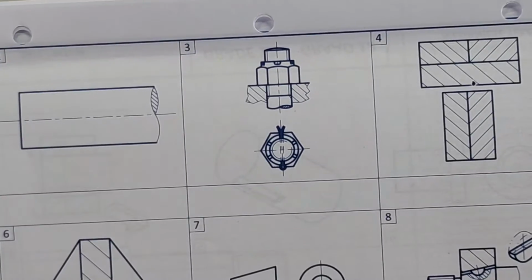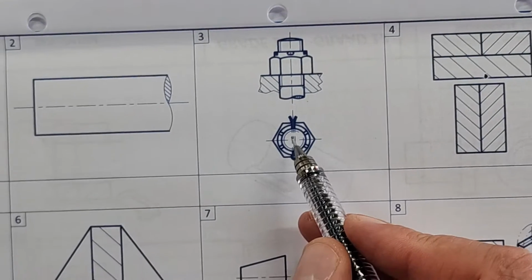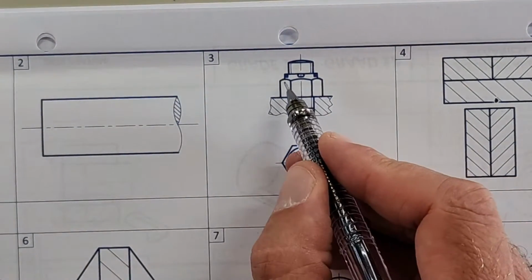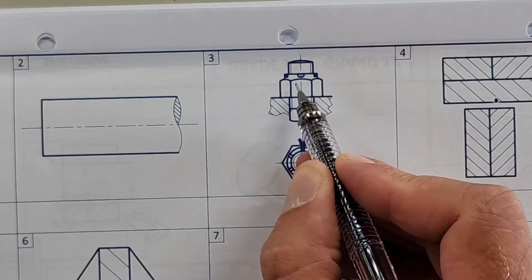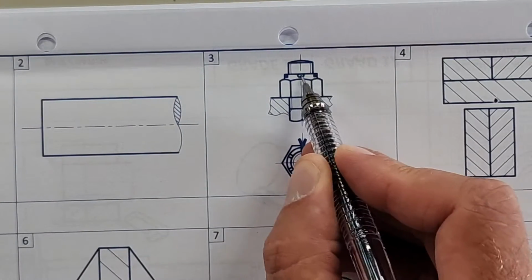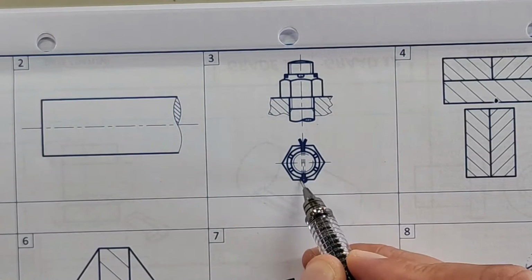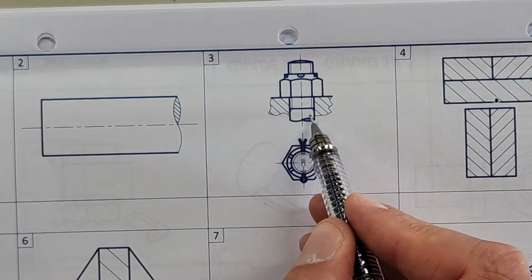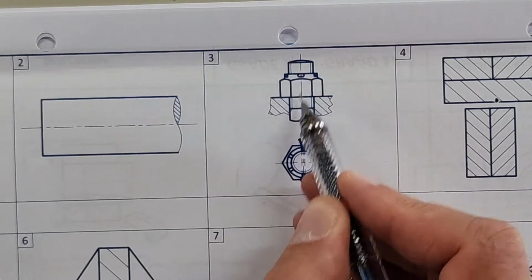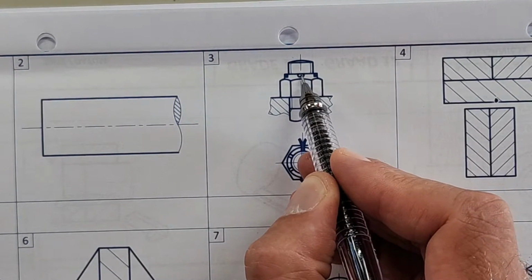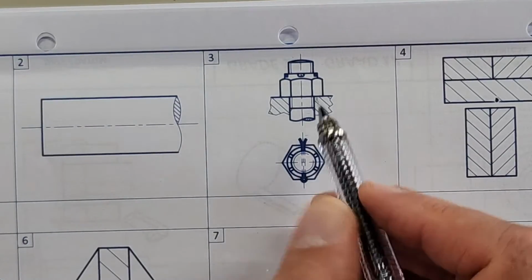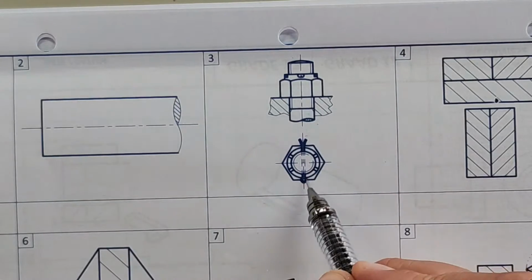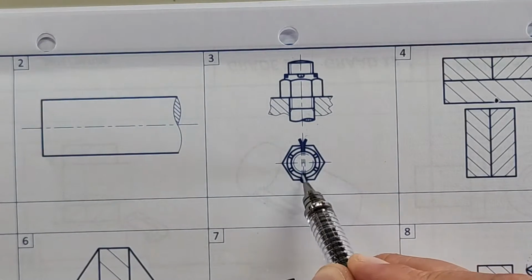Number 3 is a castle nut, or in Afrikaans, a kroonmoer. Okay. So just look at that nut for instance. What does it have? It's got openings, and I can put a pin through those, and you can see how that's going to work. That shaft has got a screw thread in, all right, and it's also got a corresponding hole going through. So if I then put my pin through, there's no way that it will be able to loosen. All right, you see that pin going through the nut and the shaft.